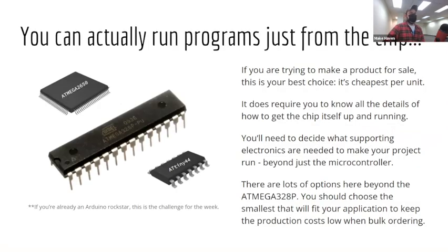So the first of these alternatives is that you can actually just get rid of the Arduino itself and just directly program the chips. Somebody in last year's foundation totally did this. It's completely doable. And if you've already got some coding background, this is a really cool way to try and level up your skill. And if you're gonna build something that you want to sell, this is how you would do it. You'd build it around something like the ATtiny44, where an Arduino, you might buy an off-brand Arduino for maybe $7 or $12 online.